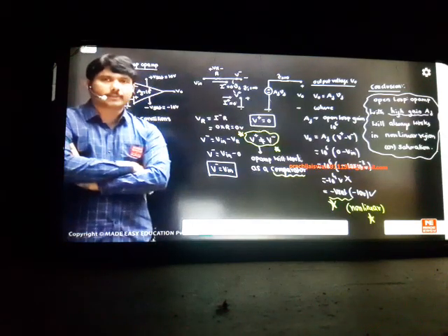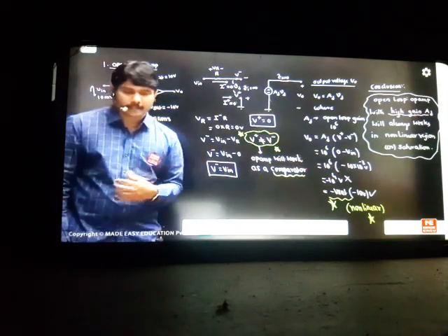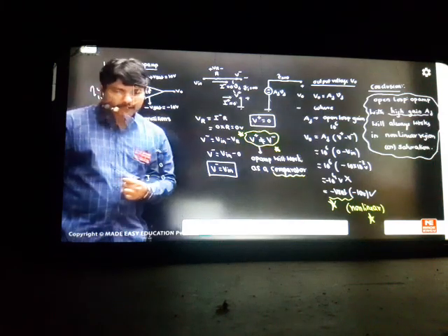Okay? In open loop op-amps, never say the words virtual short theory, because virtual short theory applies only if you can prove V plus is equal to V minus, but you have not proved it. You proved that V plus is not equal to V minus. So it is not a virtual short, it's a comparator. You have two principles: either comparator or virtual short happens. Here virtual short cannot happen. It's the comparator rule that is happening.